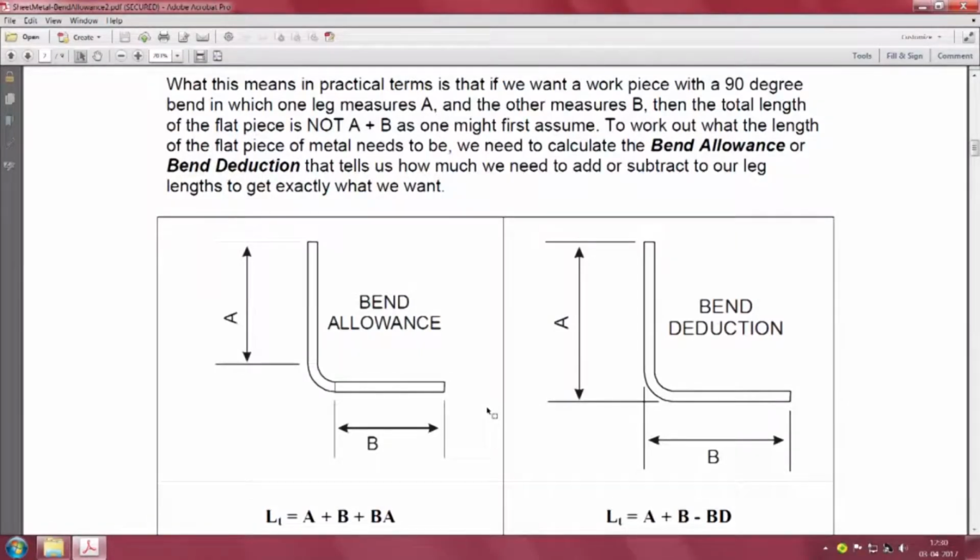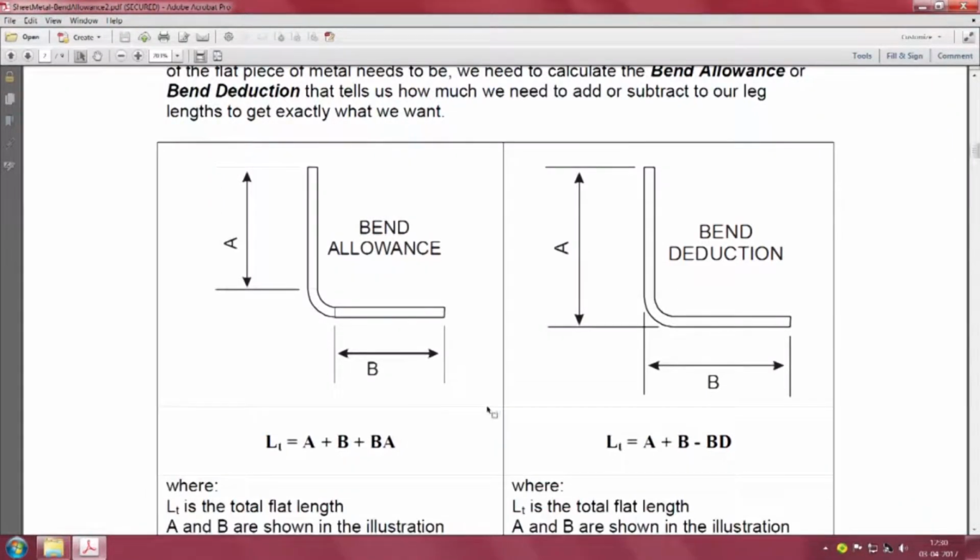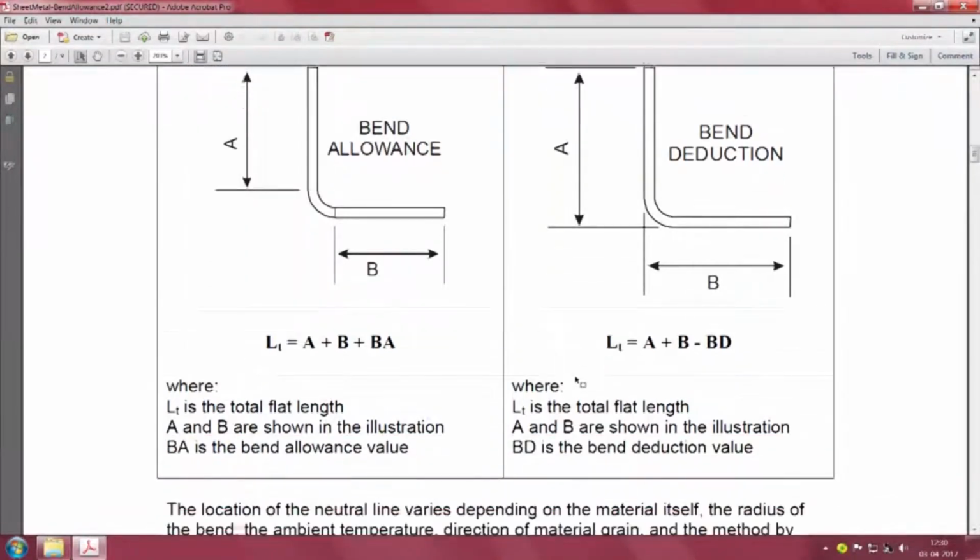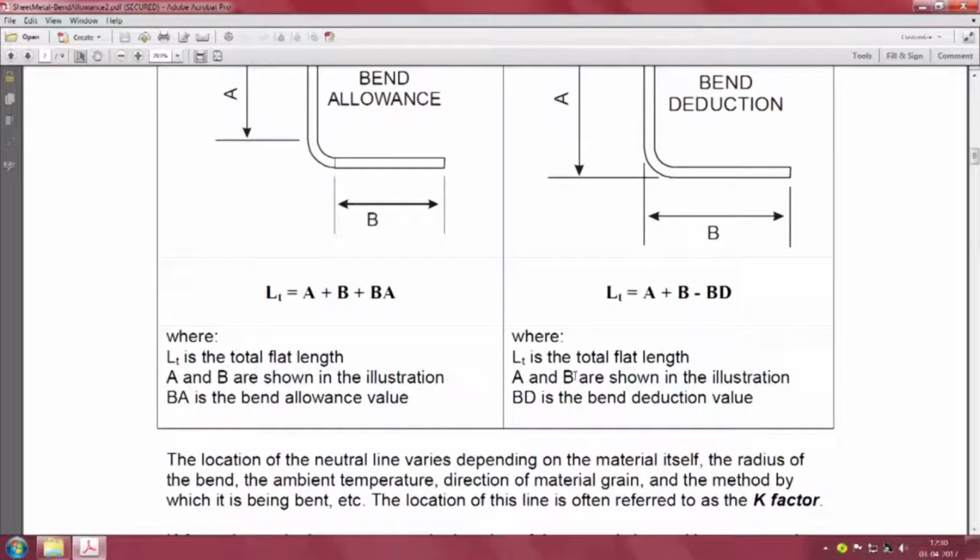The difference there is all about the K factor, saying how do you determine the K factor, and the word scientific and the word trial and error are used. Instead, here this is more related to, if you take the internal dimensions minus the bending radius, how do you add a bending allowance, or in the case you want to take the external dimensions, add the external dimensions and then you remove the internal dimensions.